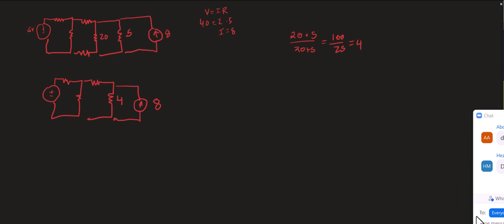Okay, so now I have reduced my circuit to that, and I see that I've got a current source and a resistor in parallel. So now I can go backwards and turn that into a voltage source and a resistor in series. So I will do so. Didn't you miss one of the resistances? The one that is in the bottom? Yes, thank you. I did.